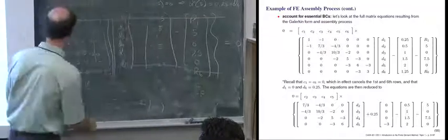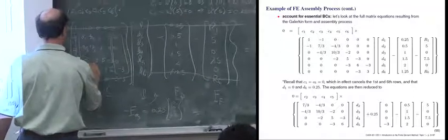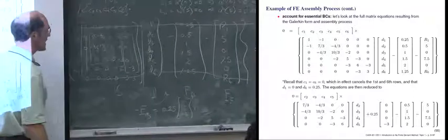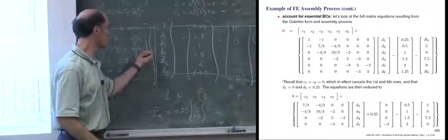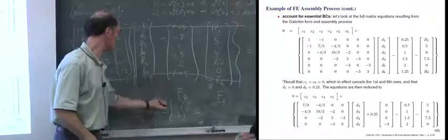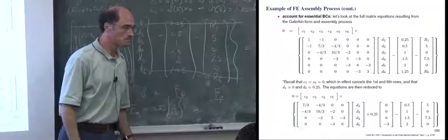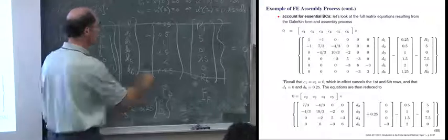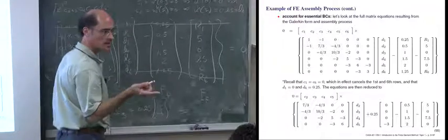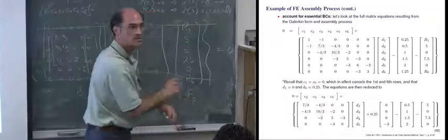So then what you're left with, which is shown in the notes, is a 4 by 4 matrix, which is now not singular, number one. And number two, we extracted the portion of the stiffness matrix that we needed to multiply by D6 to give us a forcing vector. Why is it positive in the notes if it's minus? Well, there's a minus sign here, so I'm going to write that in a second. What we do is eventually move it over to the right-hand side. So just hold that thought for a second.